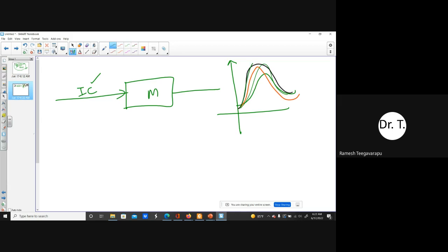So you might argue, oh, is it not something similar to sensitivity analysis? No, because sensitivity analysis is looking at how sensitive the parameters are to the output of the system, whereas ensemble-based modeling is not about sensitivity. It's about trying to generate different possible states of the system by ascertaining the uncertainty in your inputs or uncertainty in your initial conditions. So that means you can have 1,000 hydrographs for the next day, each one giving you a different peak discharge.